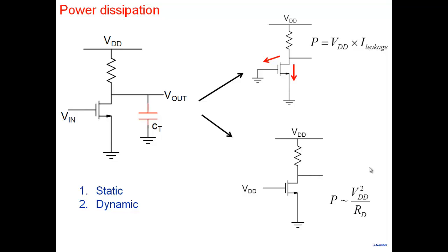So this is what I mean by static power dissipation. Static in what sense? I'm not changing the state of the node here. This node is now gone to VDD. This node is at 0. This is at VDD. These are stable. And under those stable conditions, are they taking power from the supply? Whatever power they're taking from the supply, we'll call that the static power dissipation, when the nodes are not changing, discharging, charging. That's the static power dissipation. We don't want static power dissipation at all.